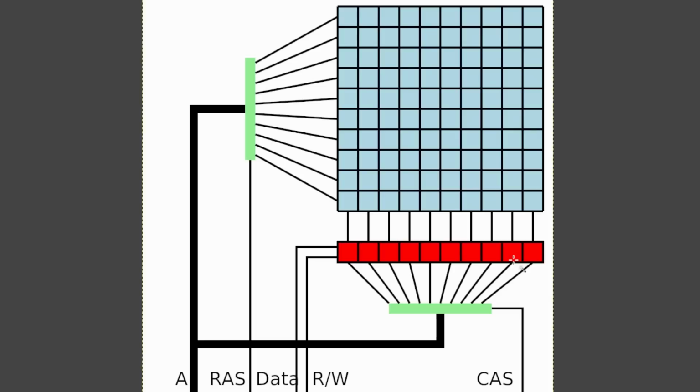And the cool thing is that in order to energize bits of memory to do dynamic RAM refresh, I don't need to access every single bit in the memory. I just need to access every single row. And so actually, if I access any bit in that first row, the entire row will be energized. So I only really need to access each row, and there are not very many of these.